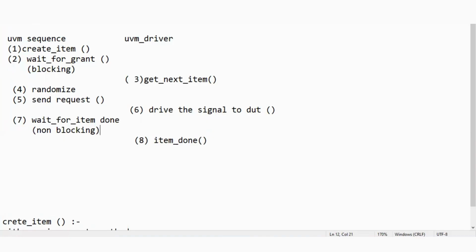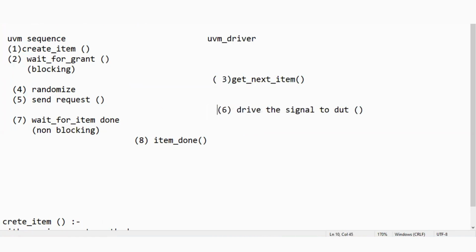No, Priya. Okay, so now see here we have UVM sequencer. In between them, for the handshaking purpose, we have UVM sequencer. So now, in a UVM sequence, you may have so many packets. You want some arbitration between them. So UVM sequencer has that arbitration. Arbitration means whatever items you have created, you want to send them to the driver on a weight basis. Like some item has more weightage, so it will be generated more times.